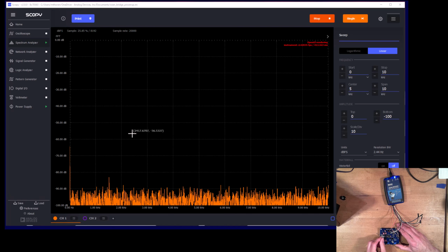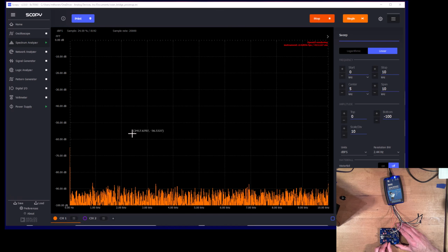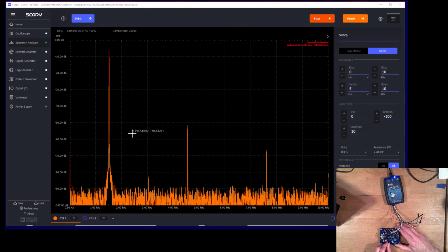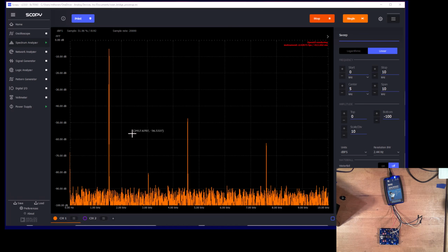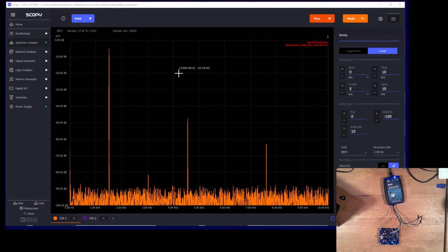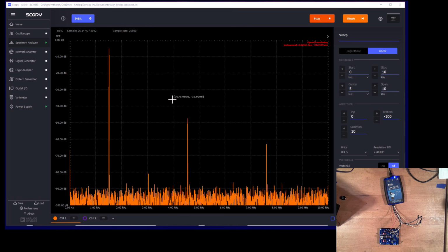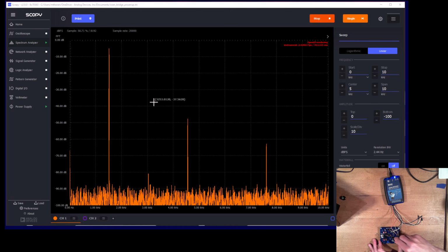So see, I tried to go up in frequency, and here I have to retweak the gain every time I change frequency. And if I want reliable oscillation, then I have to bump the gain so high that my third harmonic pops up quite a bit. So 10, 20, 30, yeah, so about 40 dB or 1% distortion here. Okay, now let's switch over to light bulb gain control mode.